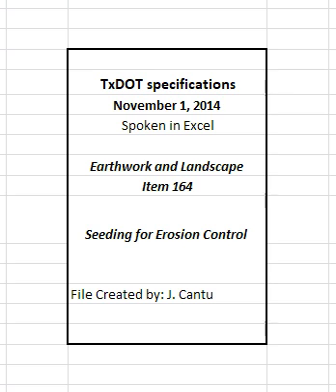3.2 Straw or hay mulch seeding. Plant seed according to Section 164.3.1, Broadcast seeding. Apply straw or hay mulch uniformly over the seeded area immediately after planting the seed or seed mixture. Apply straw mulch at 2 to 2.5 tons per acre. Apply hay mulch at 1.5 to 2 tons per acre. Use a tacking method over the mulched area.